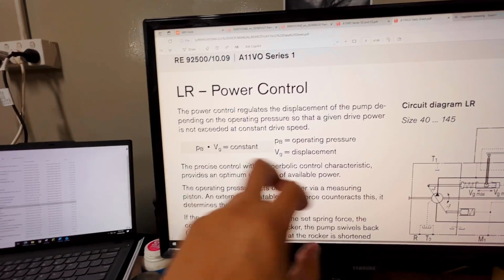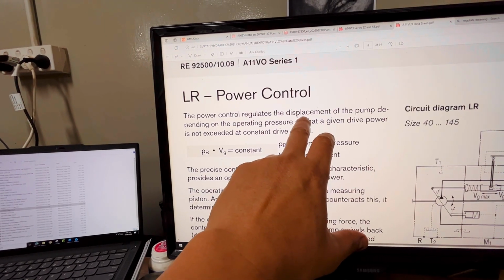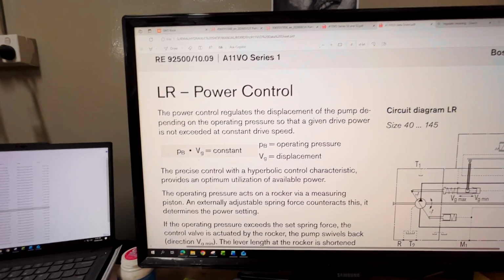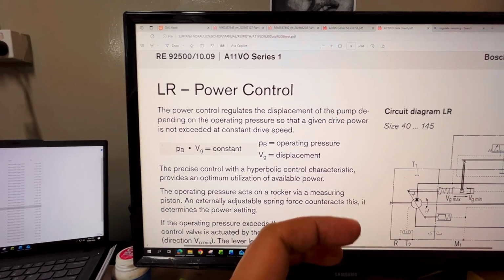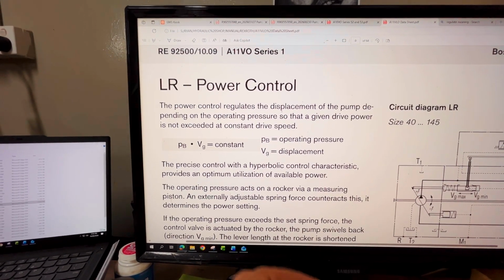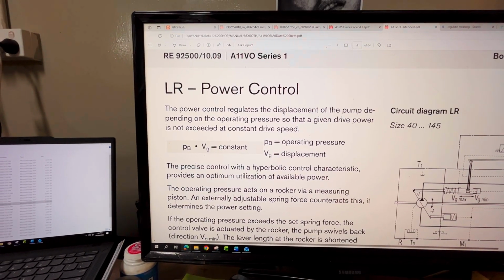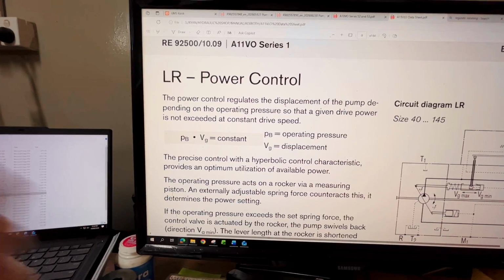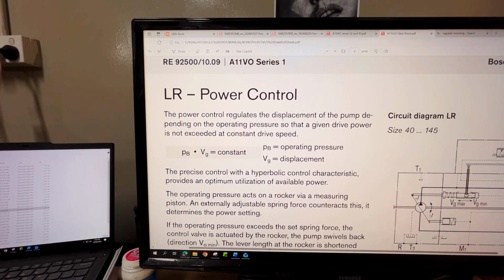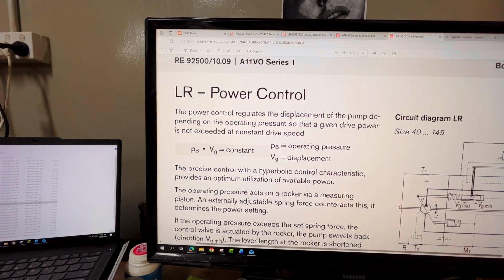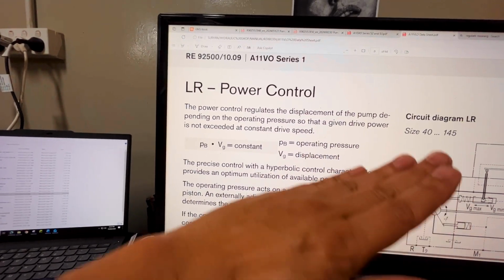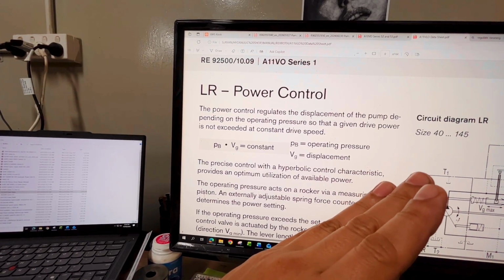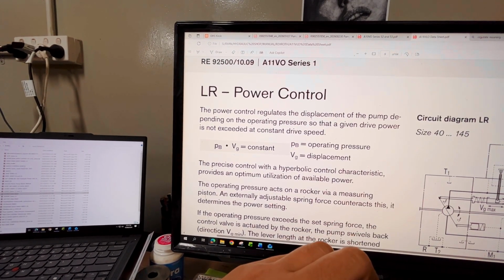So here, this displacement, which is the size of the pump, is the stroke times the area of the piston times the number of pistons. So that's the displacement, which is the cc per revolution. That's on your swash plate or cam.